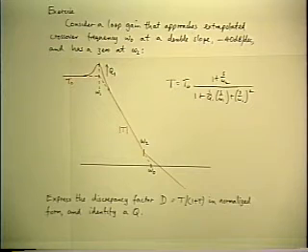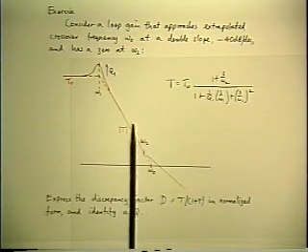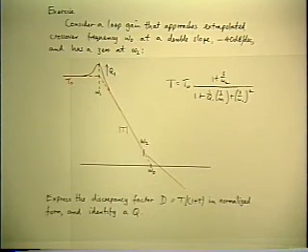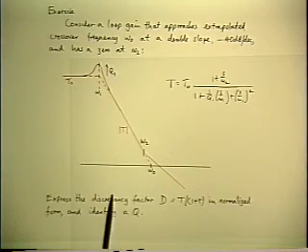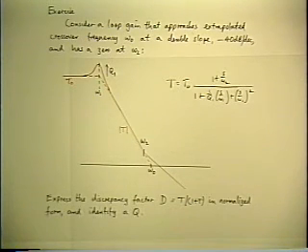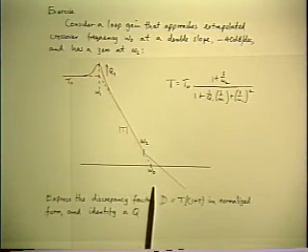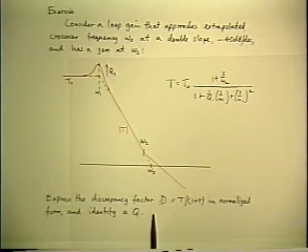And so what I've done is led you up the garden path, because the proper way to start this is simplify the problem before you write anything. And it's exactly the same simplification that I talked about in the previous case, where we had a single pole followed by a second pole further down. And I started off by saying the only part of interest in the solution is what happens near crossover relative to the position of the zero. That's the interesting part of the problem at the moment.